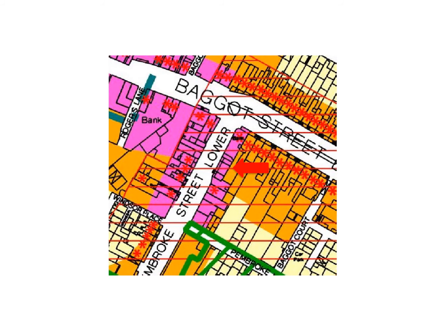This map is an extract taken from the Dublin City Development Plan. So you can get some information as to what the permissible or existing uses on the site are. This red line across here means it's in a conservation area. The green just cut off at the corner there is Fitzwilliam Square Conservation Area. Each of the red asterisks shows a protected structure. The yellow colour is conservation, and the purple in this instance is for commercial uses.